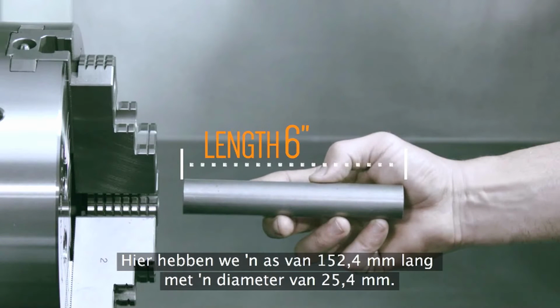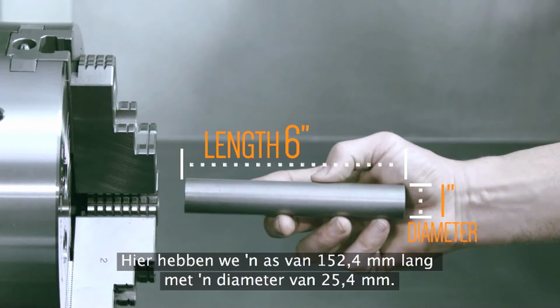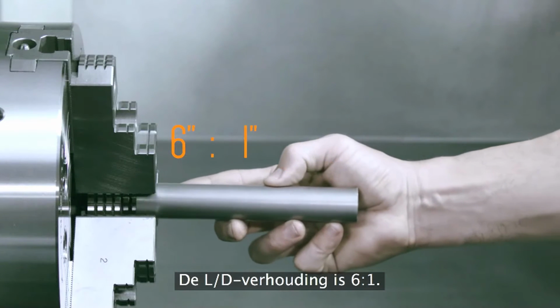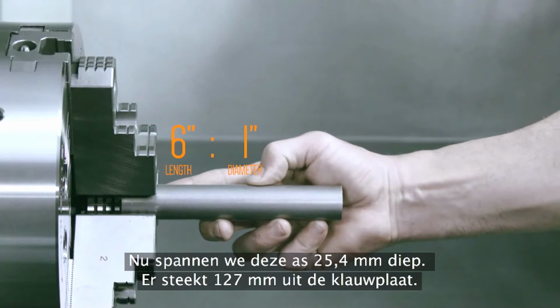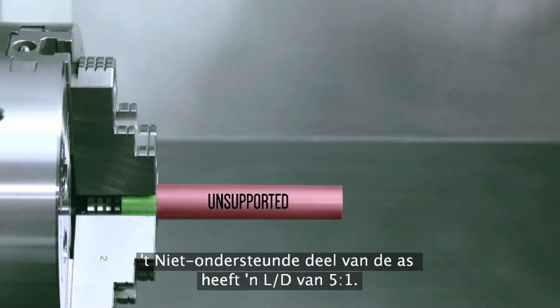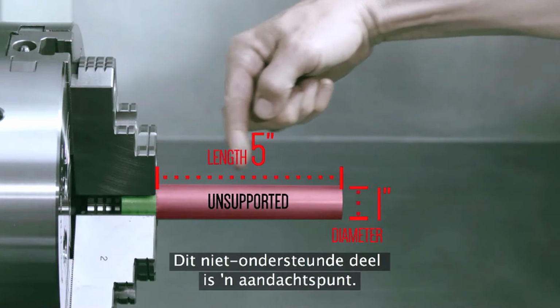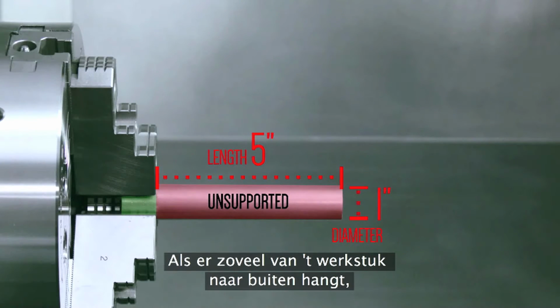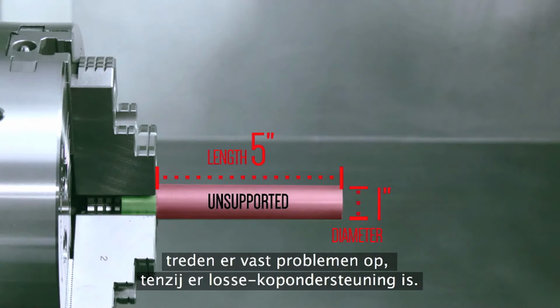Here we have a 6-inch long by 1-inch diameter shaft. Its length-to-diameter ratio is 6:1. Now we clamp this shaft 1 inch deep with 5 inches extending outside the chuck. The unsupported region of the shaft has an L to D of 5:1. This unsupported region is what we need to consider. With this much of the workpiece hanging out, there will likely be problems cutting unless tailstock support is added.